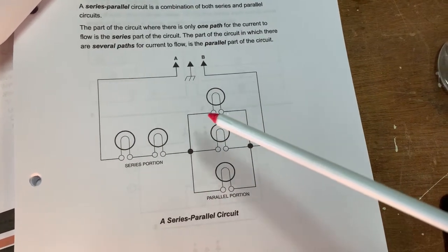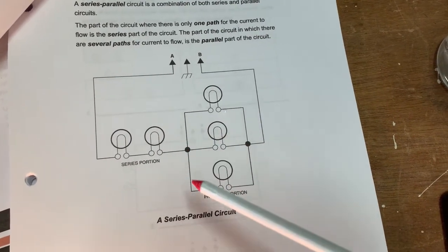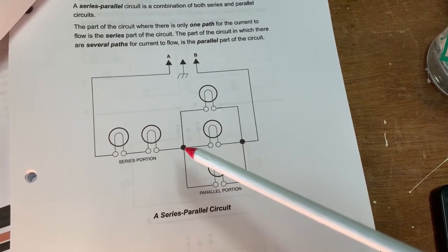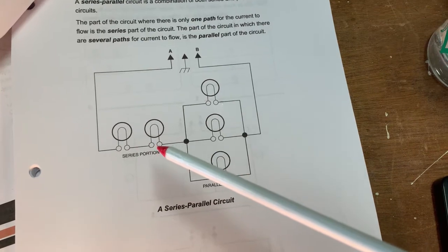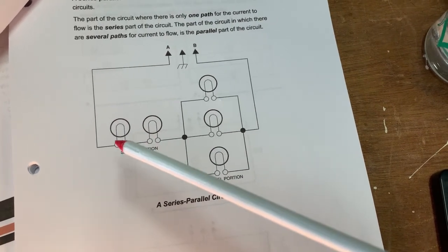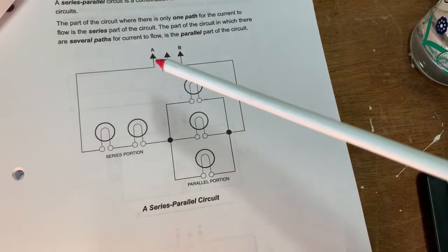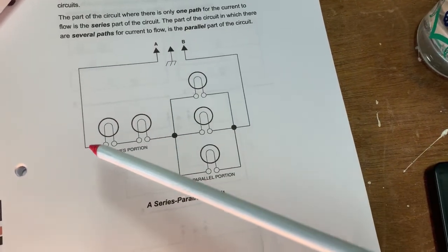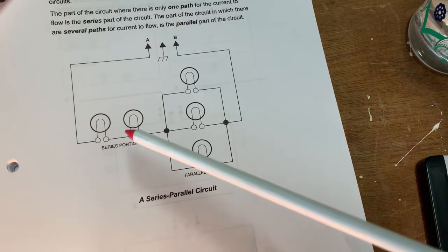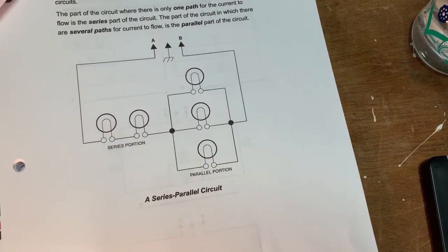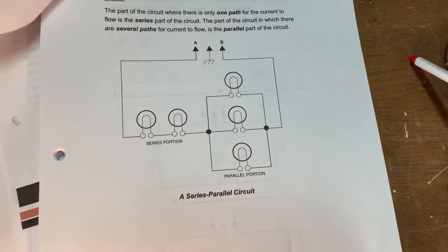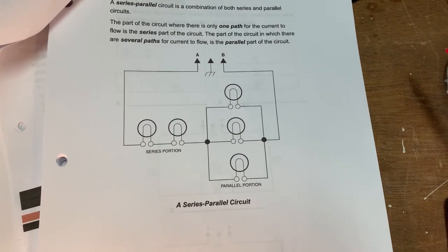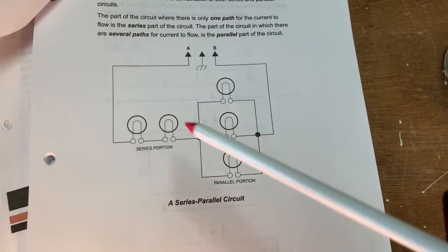And you can see individually each lamp is wired on the line side. But look where line comes from. It's going first through these lamp filaments to complete the circuit. That's line. So lamps can be used to carry voltage to another device when used in series.